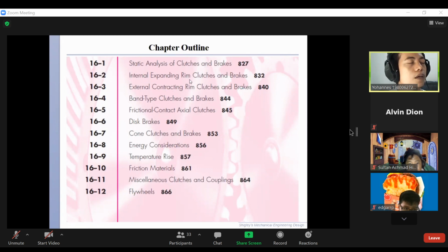So here we will follow the outline from the machine element handbook, and the topic is arranged like this. We will do static analysis for clutch and brakes. So the purpose is to identify the working force, how torque and force are related in the mechanism. Then we will use this torque and force information to calculate stress. And using this stress, we will evaluate the safety, the failure, by comparing with the strength of material.